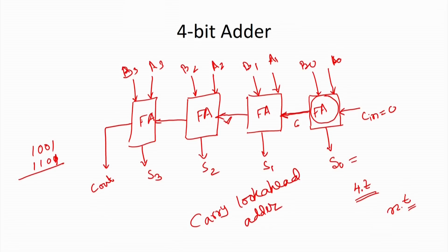Here we are not going to discuss these things, just as information I am giving you that we have another circuit known as the carry look ahead adder, where carries will be generated at the same time and simultaneously propagated. Okay. Carry generation and carry propagation. So, with the help of this carry look ahead adder, we can reduce the propagation delay of the adder.